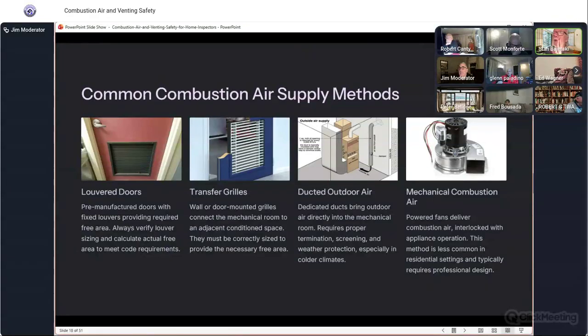So finally, I guess the big guy came down, and he found a leaf in the makeup air pipe from outside. A leaf that lodged itself in there because there was no screen and blocked enough of that pipe that they weren't getting enough combustion air. Now, luckily, there's an interlock and it shuts it right down. So once he found the leaf and cleared it out, they put a screen on the pipe, and they've been fine ever since. So that was a scenario that has a safety on it.